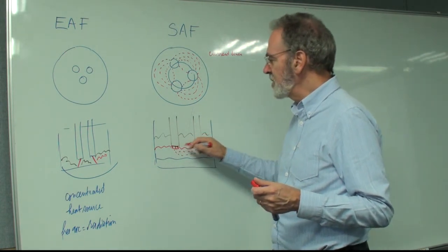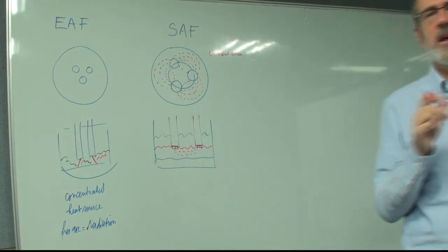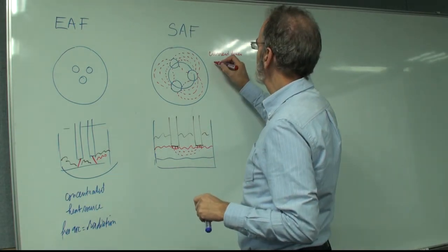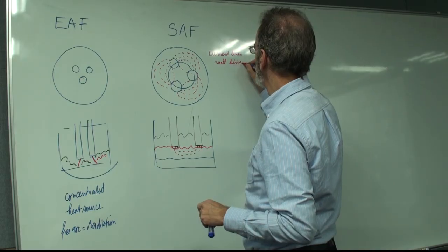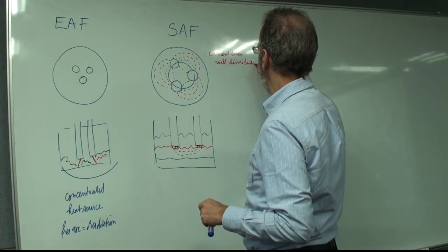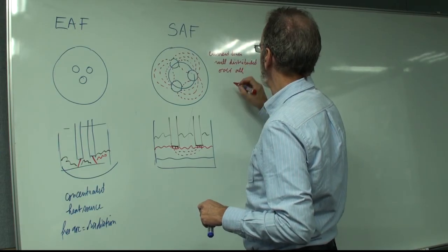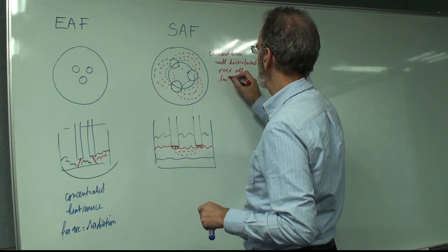Also the arcs, but the arc heat will be catched by slag, no problem. But the current lines must be well distributed over all bath surface.